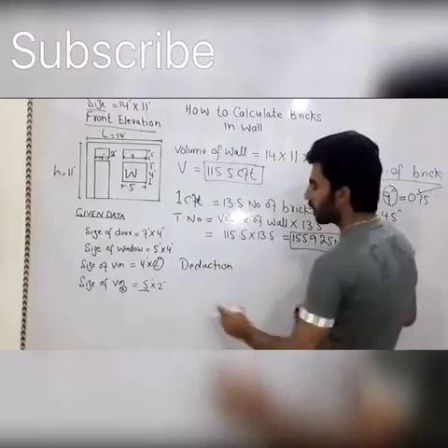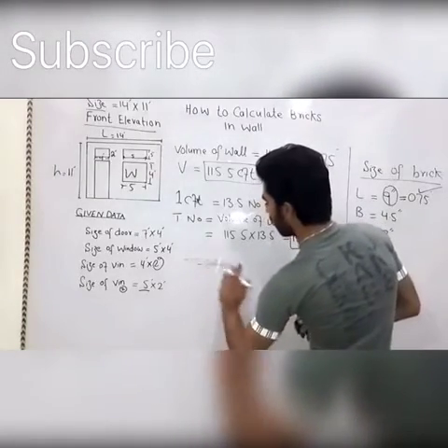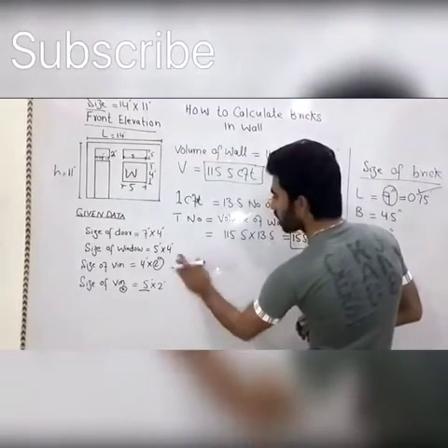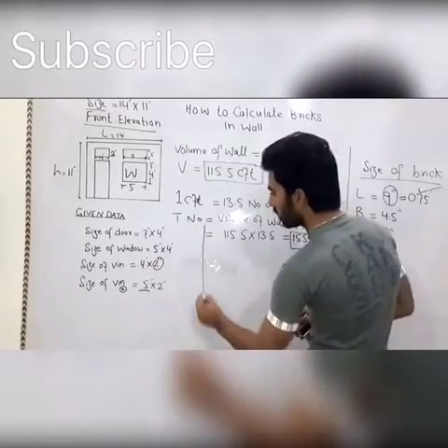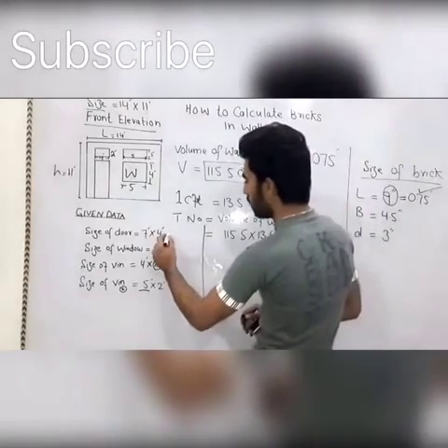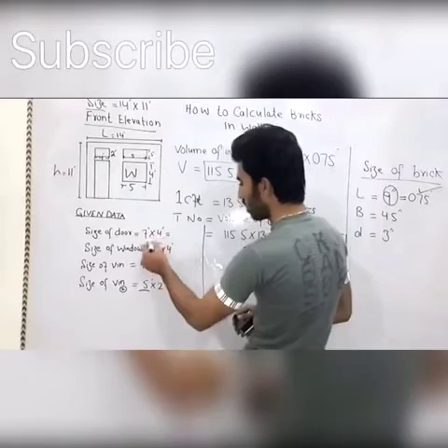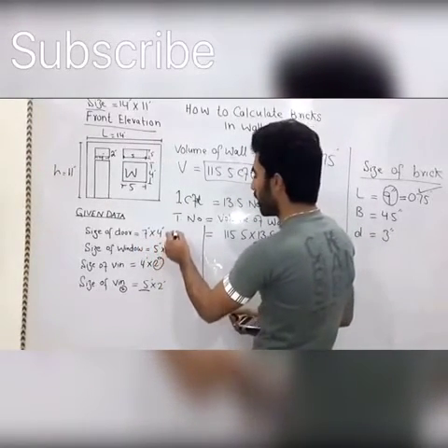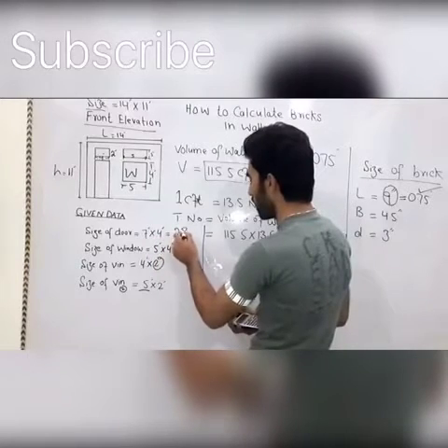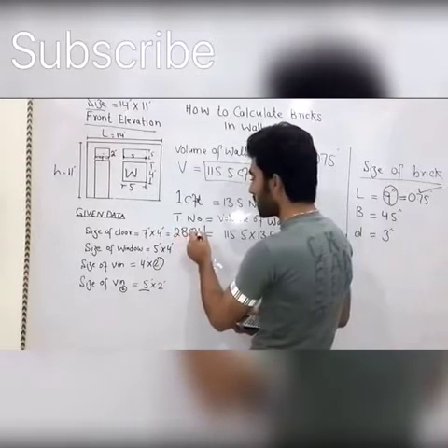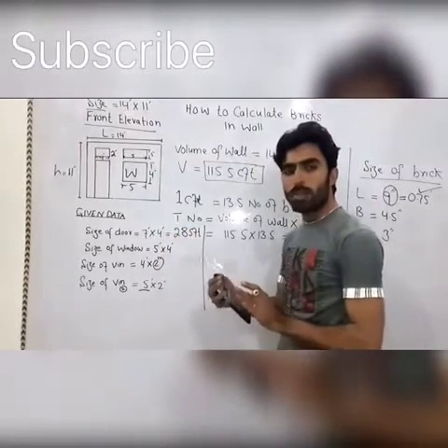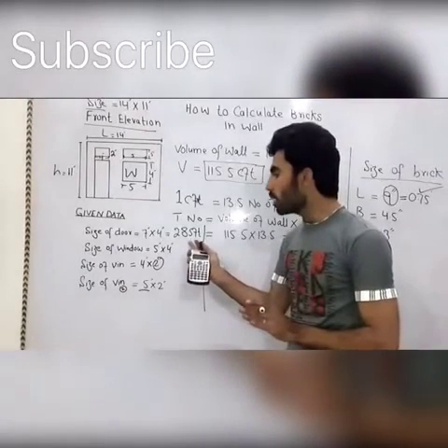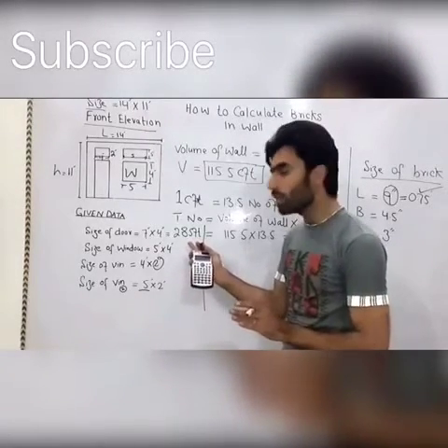And deduction you can, so I will write here. Okay, so first of all, 7 by 4 gives us 28 square feet. Okay, this is the area. After that I will multiply by the thickness of the wall, so it will give you CFT, meaning cubic feet.